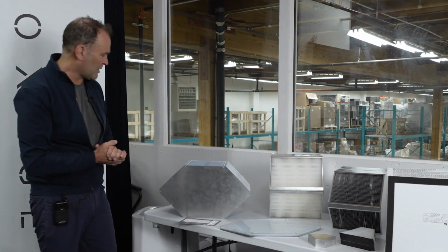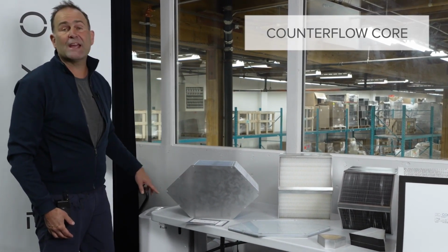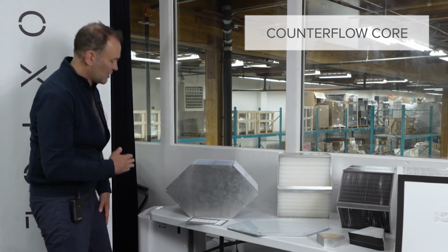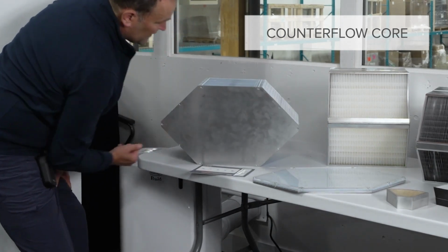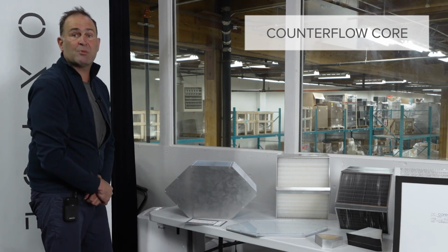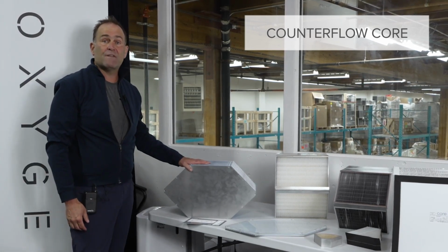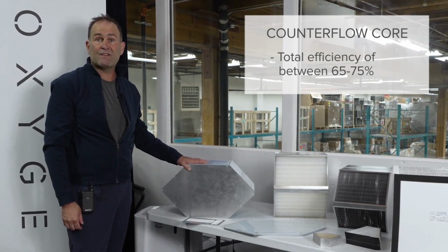More recently in North America, we've started to see these high-efficiency counterflow cores, which are the hexagon shape, and the two air streams are parallel and opposite to each other. So you'll have the return air go through this side of the core like this, and then you'll have the outside air go through to the supply side of the building here. Typical efficiencies of the counterflow core are somewhere between 65 and 75%.